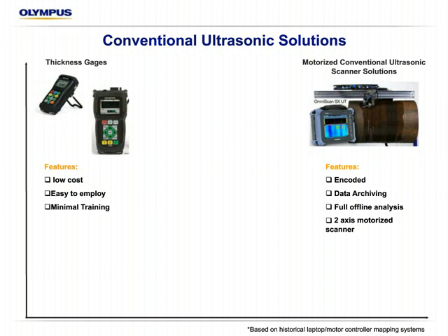Typically the conventional ultrasonic methods for detecting corrosion are on one of two tiers. On the low end, we do point measurement or data logging with thickness gauges. So that's an ultrasonic sensor with either a numeric readout or a waveform readout of the energy along with a reading. These measure the thickness only at the point where the sensor is located. A lot of good features for these, a lot of them out there, and it's obviously the easiest and most inexpensive way to measure corrosion. Doesn't take a lot of training, very easy to use.